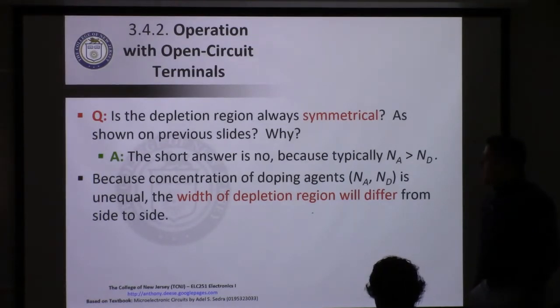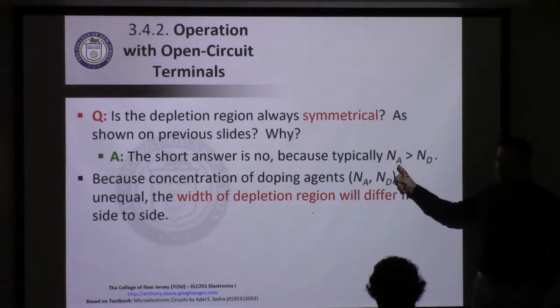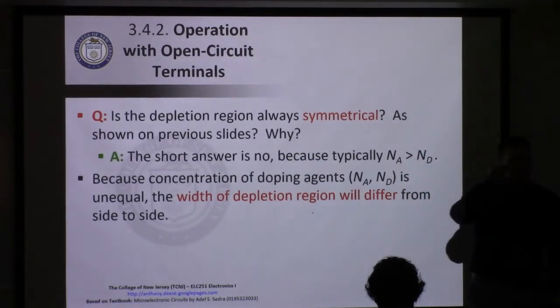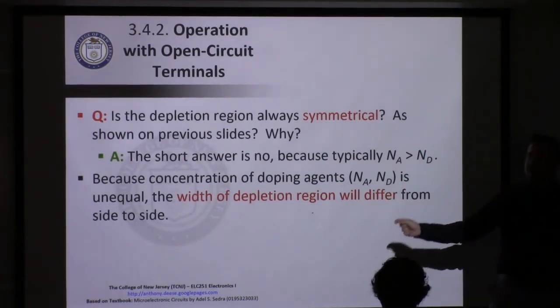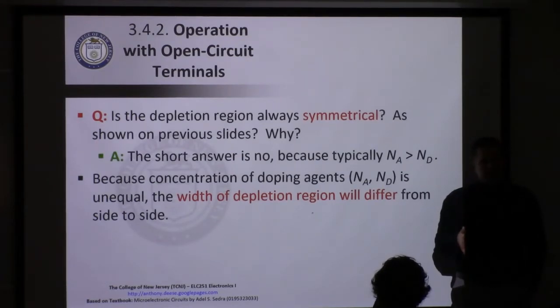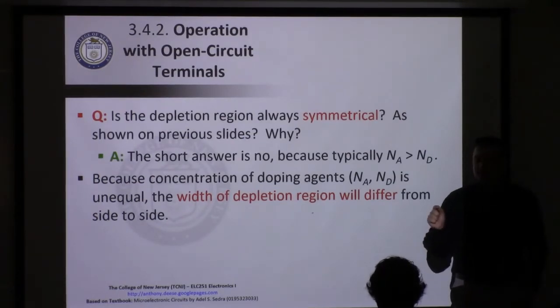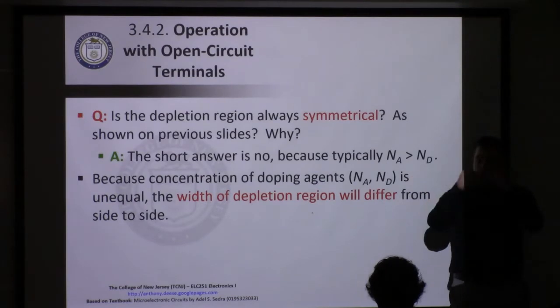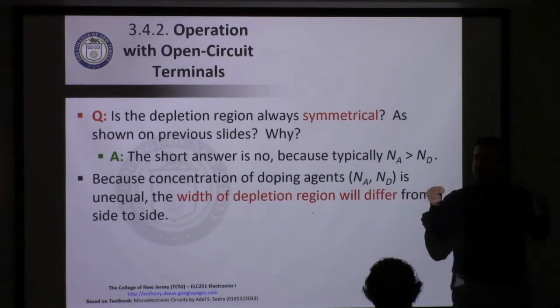The reason why is because the real limiting factor is that the amount of charge on the left-hand and the right-hand side needs to be equal. If we have 4 electrons on the left-hand side, we need 4 holes or positive charges on the right-hand side. It needs to even out. And that makes sense because it's created by the majority charge carriers canceling out. So one uncovered bound charge is only created when another uncovered bound charge is created.